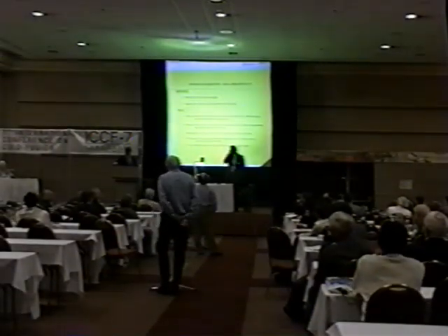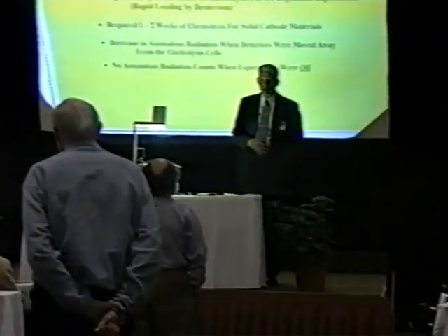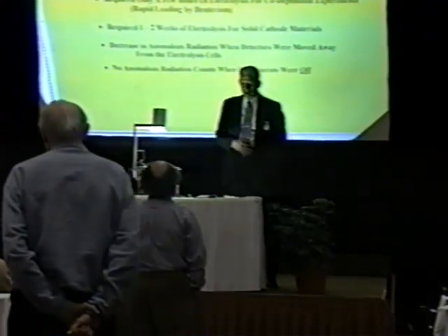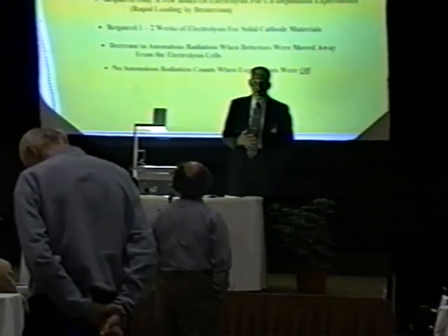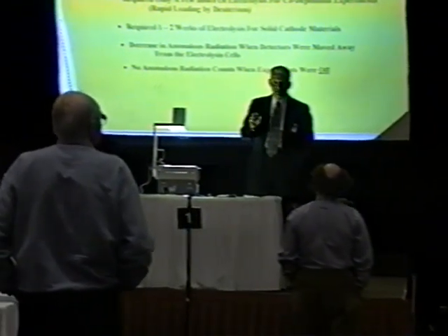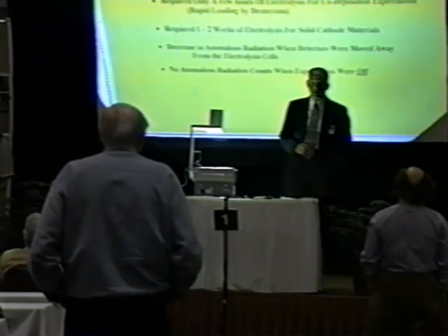When you did your co-deposition experiment, what kind of cathode did you use as a substrate? We always use a copper substrate, but I think Stan Spock has used other things like nickel perhaps. But everything we did was always with a solid copper rod that we deposit the platinum onto, about the same size as the plate electrode that we usually use.